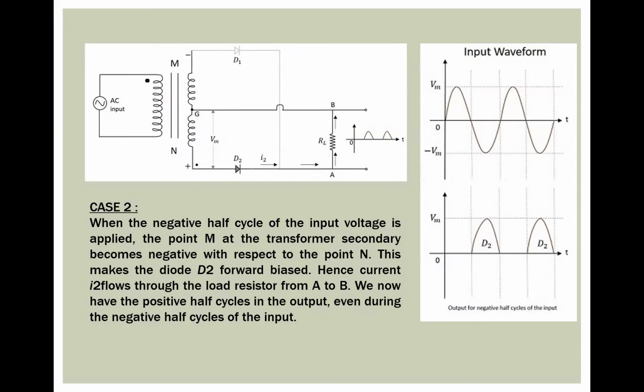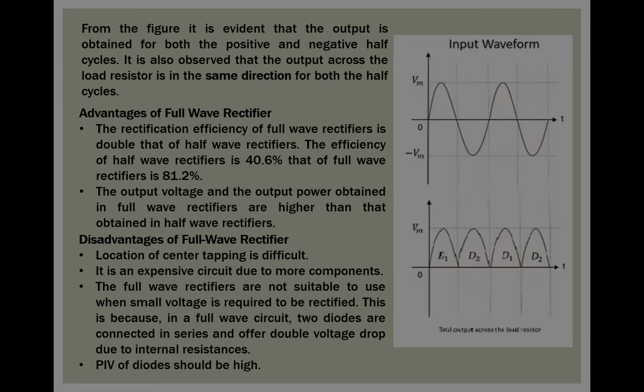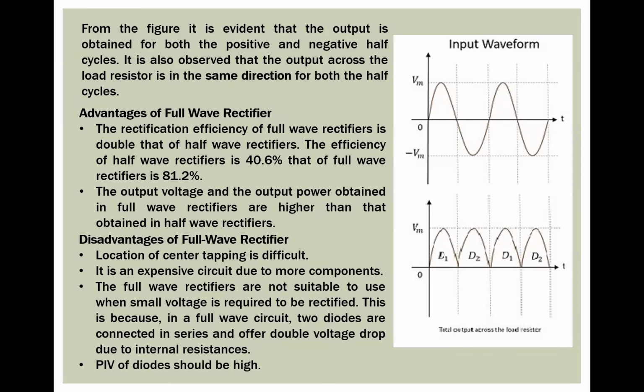it will conduct only the negative half cycles, and the negative half cycles will conduct from the input to the output, so that the input is transferred to the output. That is the purpose of diode D2. So coming to the final output, the total input, the sine wave, both the positive peak and the negative peak, is totally presented at the output. First D1 is present and D2 is present. Next, again D1 is present, again D2 is present. Now, this is about a full wave rectifier.